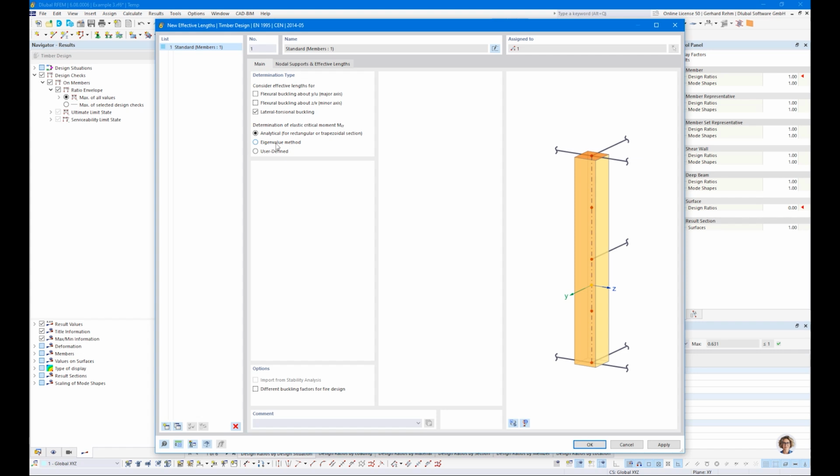I will show you afterward, which helps you to consider more options instead of settings described in the Eurocode, which is really limited to uniform loads, to a simple one-span beam, and so on. This eigenvalue solver helps you by not using these tables from Eurocode and have it considered in a common way to determine the critical bending moment.